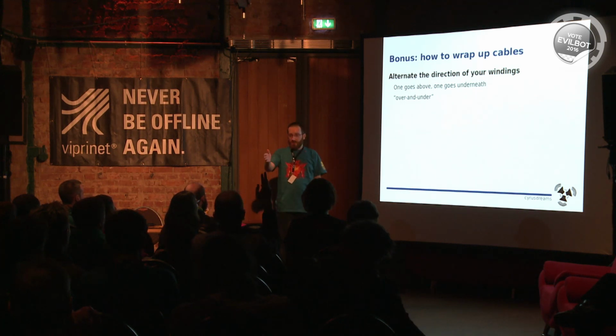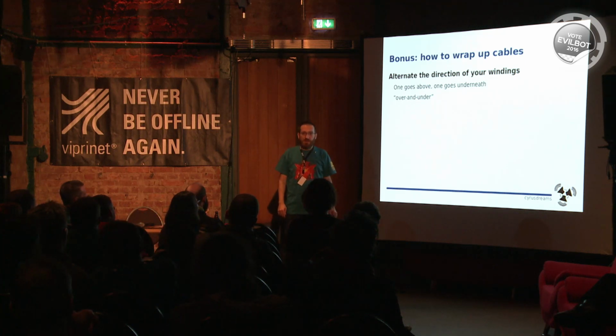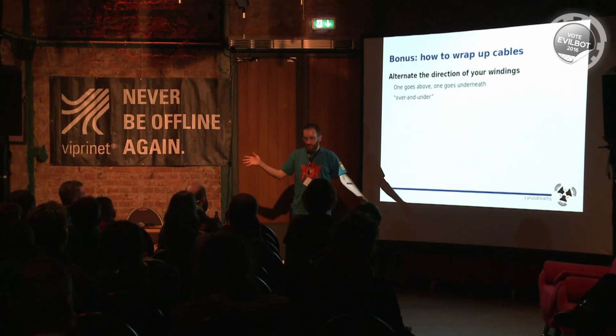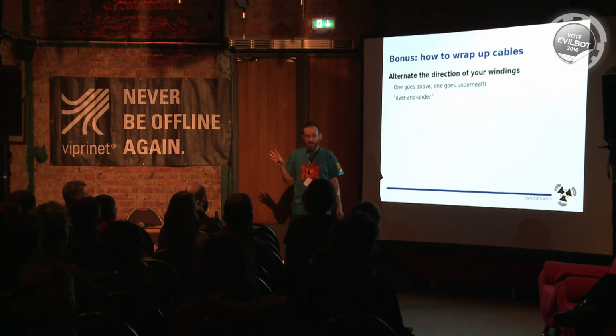Additional question? Yes. Cable length for HDMI and SDI. So HDMI, let's talk without in-between amplifiers. You have, for example, one meeting room, then you have one length of HDMI which cannot go up to 4K, but it barely manages HD.